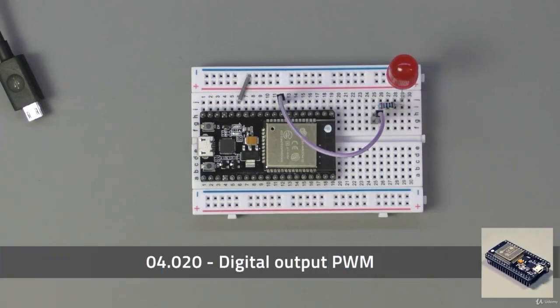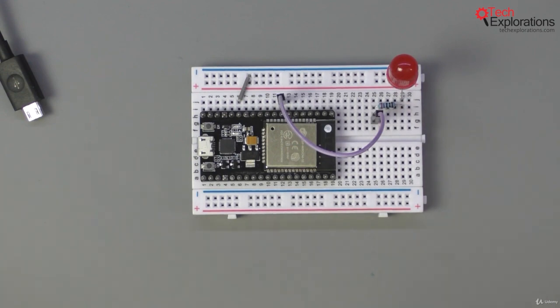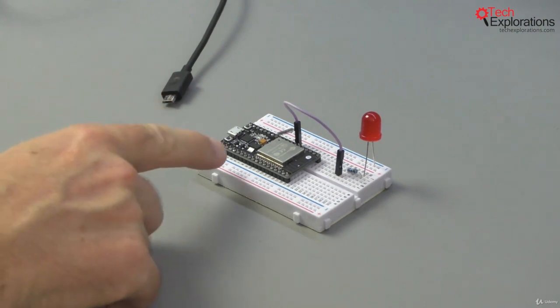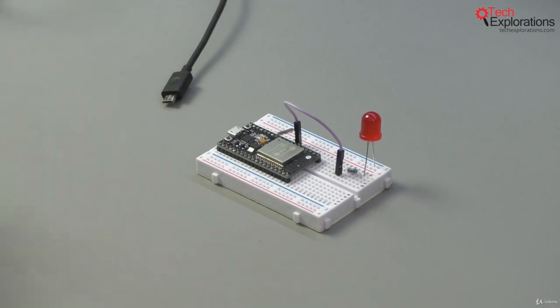Hi, in the previous lecture you learned how to get the LED connected to an ESP32 to blink, and in this lecture I'll show you how to make it fade by using the PWM capability of the ESP32. The Arduino of course can also output PWM, but as you'll see in this lecture, the ESP32 has got several additional capabilities in its hardware that the Arduino, at least the Arduino Uno with the Mega 328P, cannot even imagine, as you'll see very soon.